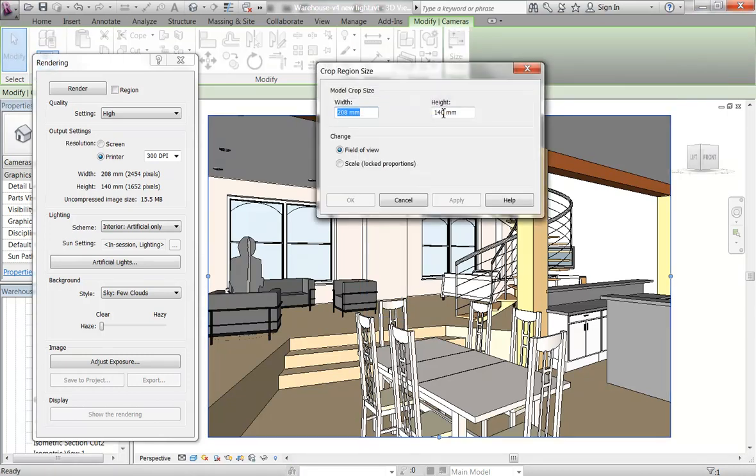So whenever you change the size here, if you're just trying to change the finished size, change it to scale down at the bottom, and that's much better. So now I'll just put in the width again, 420, and there we go. So the height now changed to 283 because it's in proportion. If I make it 297, the width will be bigger, so I'm going to leave it at that. That's pretty close to A3.